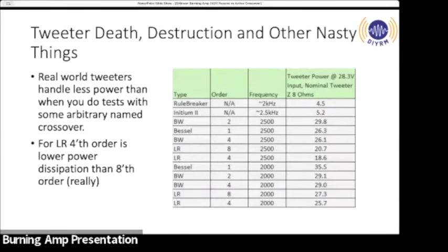And that's because the electrical filters for this don't look anything like these named ones. These named ones come from communications systems largely, except for Linkwitz-Riley, which comes from the speaker world. But these all come from mathematical poles and zeros. And really, I don't use these. Like, I never apply this. I'm doing something else to yield an acoustic transfer function that I want. I don't care what the electrical transfer function is, as long as it's reasonable and gets me the acoustical transfer function that I want, okay?